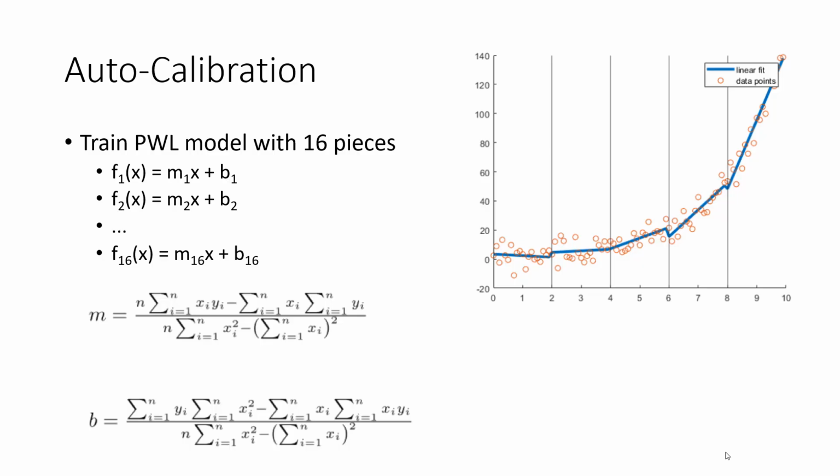Well, use a piecewise linear, PWL, which I always confuse with PWM. PWM is pulse width modulation, PWL is piecewise linear. I always screw that up. Piecewise linear is when you can trace a nonlinear curve by dividing it up into segments where each segment is linear. So you just build up a curve from linear segments. In our case, we're going to use 16 linear segments.